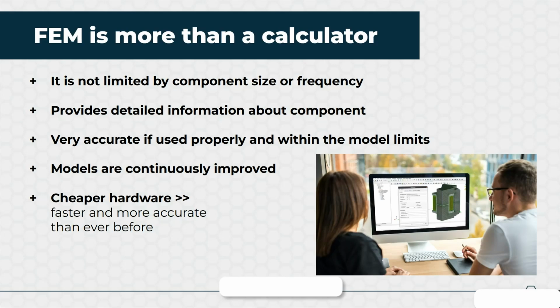And we are very often asked questions such as, what are the size and frequency limitations for 3D FEM? As we discussed before, it relies on numerics and physics. It doesn't know about the size of your component. It doesn't care about the size of your component. You can make the smallest component or the largest component. The only limitation in the context of size and frequency is the so-called low frequency assumption.